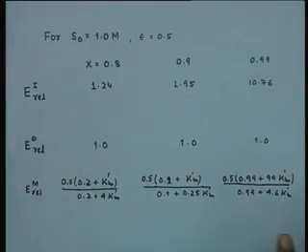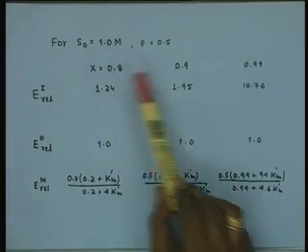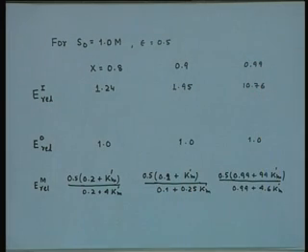Now, just to give you a bit of quantitative picture under 3 distinct conditions, here I have taken 3 different fractional conversions, 0.8, 0.9 and 0.99. Of course, I must also state here that ideally for most of the enzyme catalyzed reactions, we will try to aim at fractional conversions as high as possible. Of course, 100% is perfect, but very often you may not be able to touch that, and one may like to have fractional conversion anywhere between 0.9 and 0.99. That is usually the pattern if the reaction is practically irreversible.